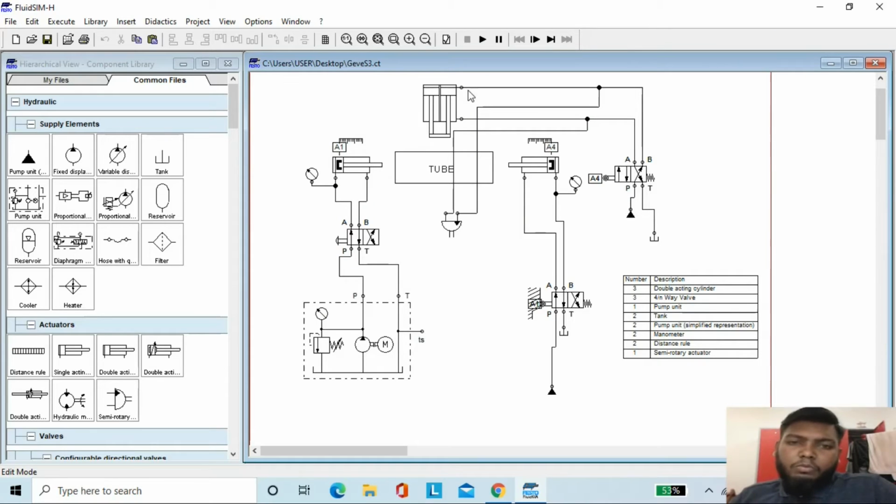Okay now, let me explain. The tube is actually placed at rest at first. The double acting cylinder, which is acting as the end cylinders at low pressure, advances and centers the tubes. The two piston rod double acting cylinder represents the clamp at high pressure. Once it is in place, the pressure at the double acting cylinder is increased and it forces out and clamps the tube at both ends.